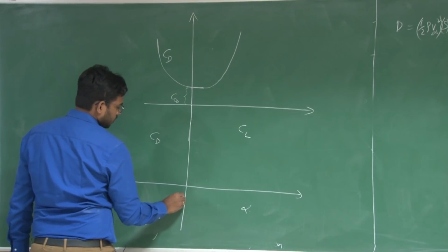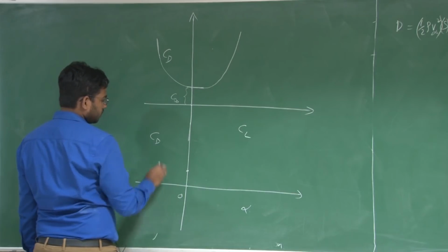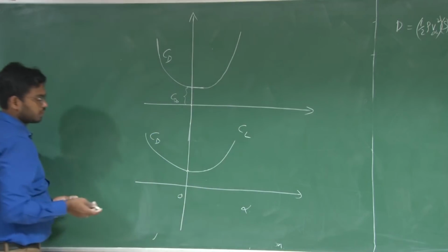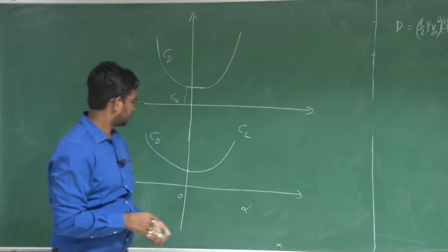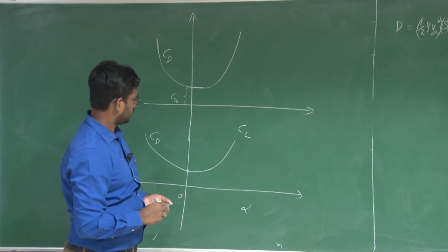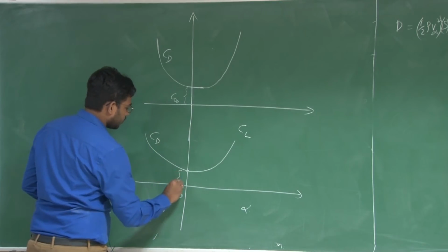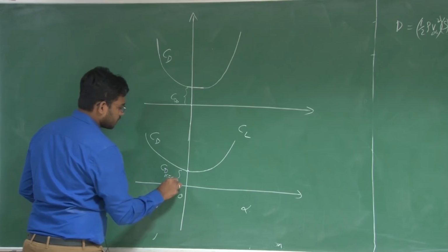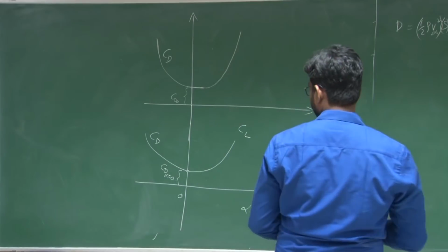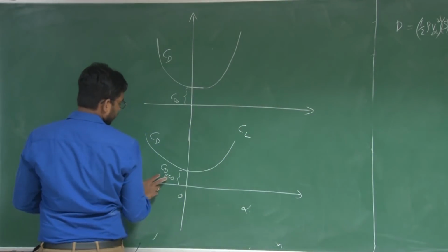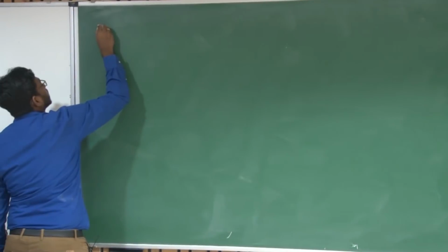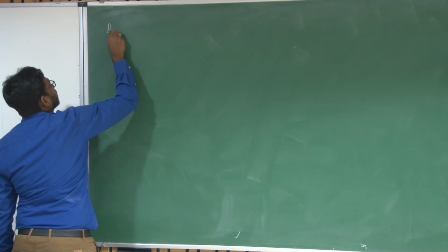At angle of attack 0 you have CD, and CD increases with angle of attack on either side. This particular point is CD when alpha is equal to 0. This is not CD naught. So you have to be careful about using CD when alpha is equal to 0 and CD when CL is equal to 0. Let us look at airfoils.